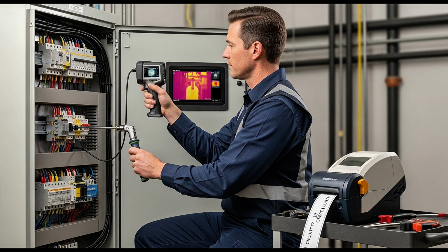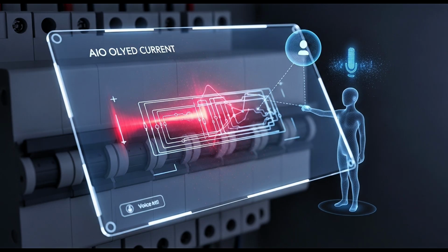While point-of-use surge protectors at outlets help, whole-panel surge protective devices installed at the main panel can stop surges from entering the building's wiring in the first place. These are becoming standard in areas with frequent lightning or utility switching transients.